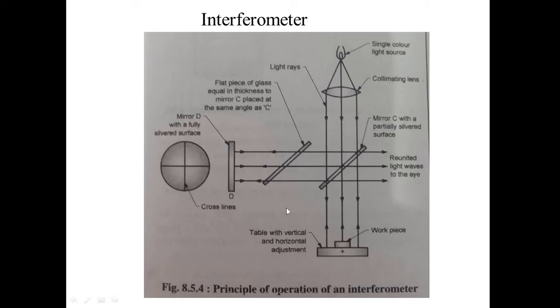One fringe pattern is due to the path difference between the surface of this mirror and the table surface, and another is between the waves reflected from this surface and the top surface of the workpiece. So by comparing the fringes obtained on the table and workpiece surfaces,